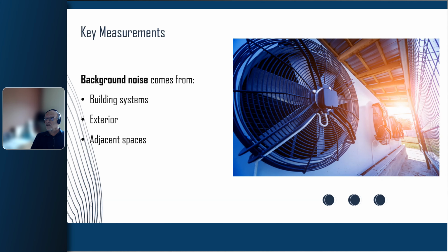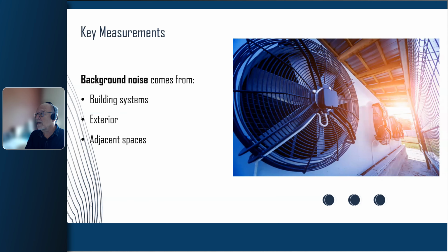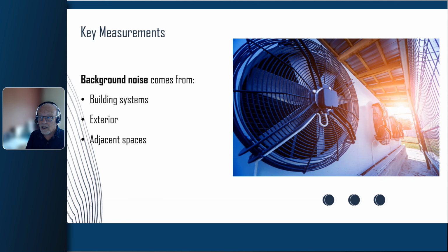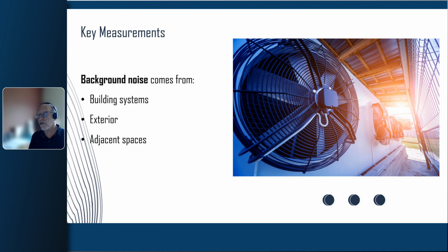But if the installation of the wall, for example, is not great, or the floors are not perfectly flat, then you're going to know when you do that NIC test that there is a problem. But identifying what that problem is means you're going to have to get the trades, or certainly the contractor, involved, to say, hey, I specified STC 50, the NIC is coming out at 38.